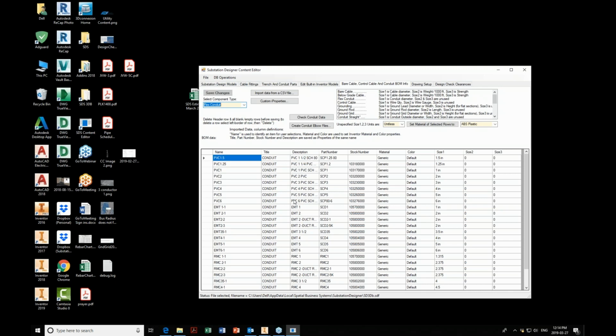but as soon as we come above ground, we have a different type of conduit. We'll have the EMT conduit, we'll have the RMC conduit, different types. And for you guys to know, it's rigid metallic or electrical metallic, and the electrical one is welded, so it's not used too often for above grade outdoors. And we have the RMC. So I add these in here so that we have these choices. It's not all your flexible conduit that you think of, bendable with the black outer layer, but this can still be a rigid conduit, but we're using the flex conduit tool for this.